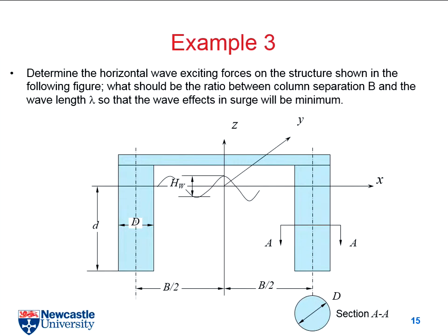And the condition we can apply Morison equation is that the structure length is very small compared to wavelength, right? And we can just assume that to this disk, the wave is like this because it's very big. That's the reason why we can assume that on this point, after we have P, we can use the P on all the area. But if we have a question in this page, we have a simplified platform and we have only 2 columns.